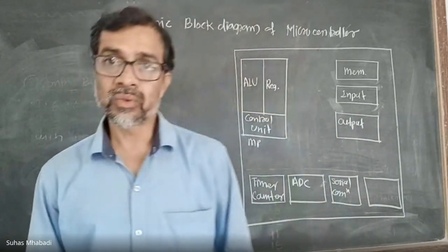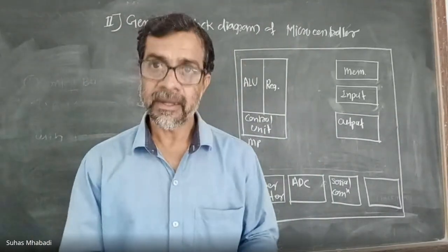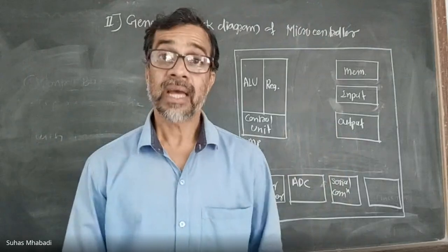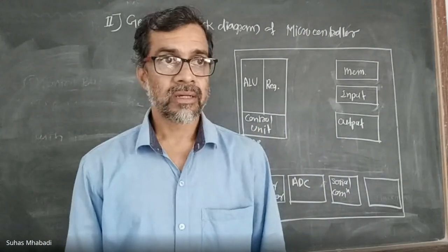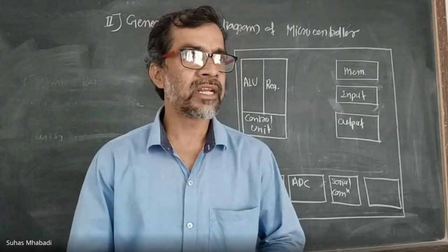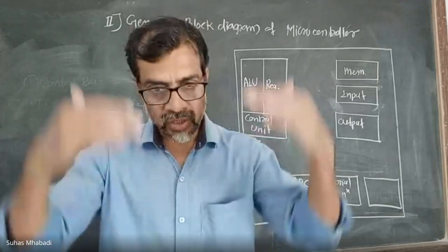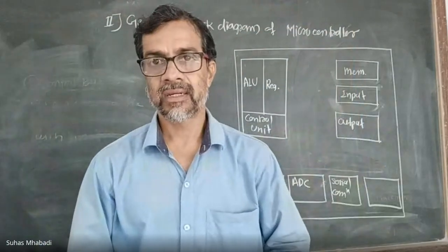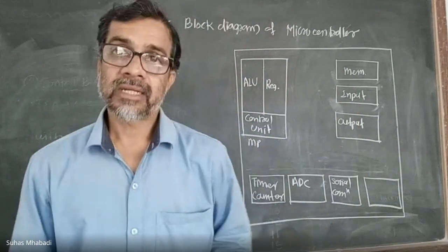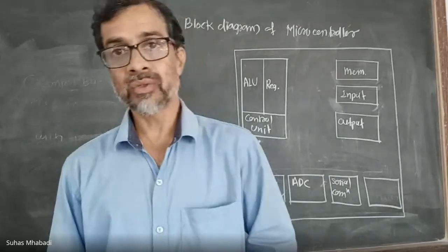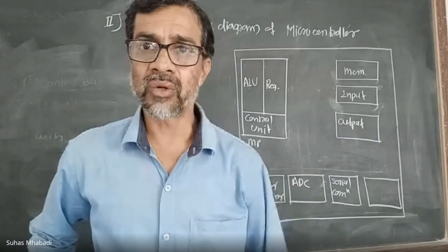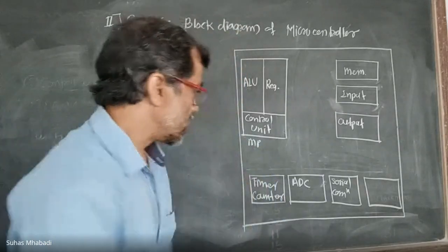my wish is to copy the content and paste it to another location as fast as possible. With normal processing execution or program, it requires almost double the time. To reduce the time straight away to half, we require one more device. That's a DMA, direct memory access. This is used to expedite the process of transferring the content from one location to another location. That is also there.